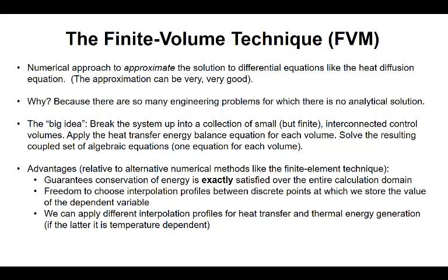This advantage will become more clear when we look at how to derive the governing algebraic equations associated with the finite volume method. The last advantage is that we are allowed to apply different interpolation profiles when we are looking at different processes within the volumes. For example, we will apply one interpolation profile when considering conduction heat transfer, and other interpolation profiles for processes such as thermal energy generation or convection heat transfer at the boundaries. In the future parts of this lesson, we will dive into the steps required to execute a finite volume analysis in further detail.